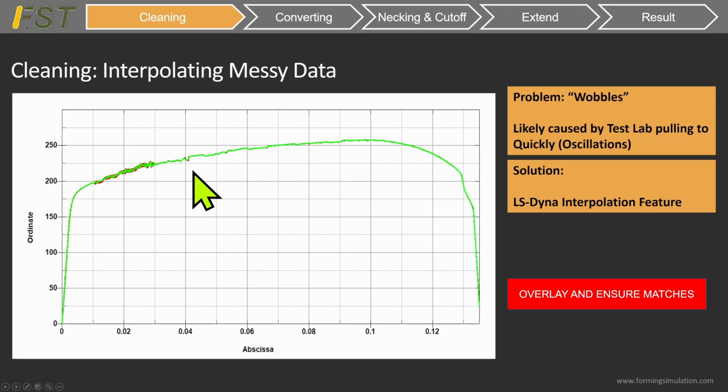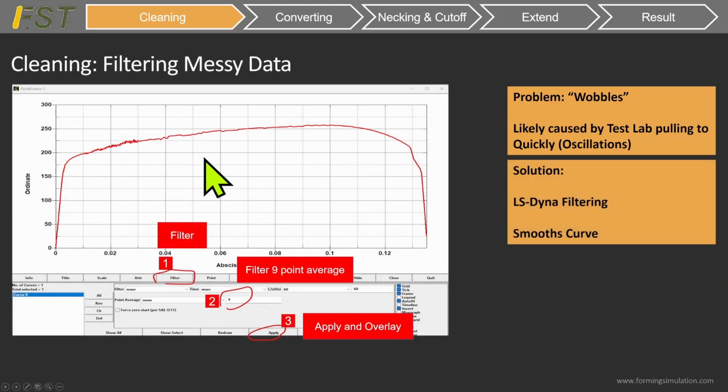So this is 401 points. In our report, 200 and 401 seems to work well, but this is where some trial and error is expected. Okay, once we have the interpolated data, we still need to correct the wobbles by doing the filter.